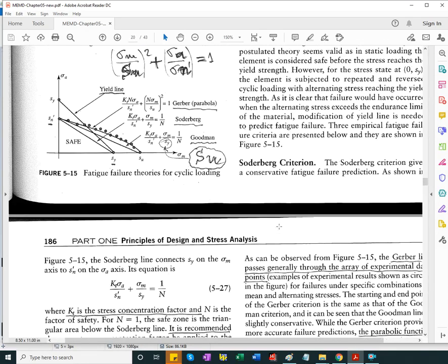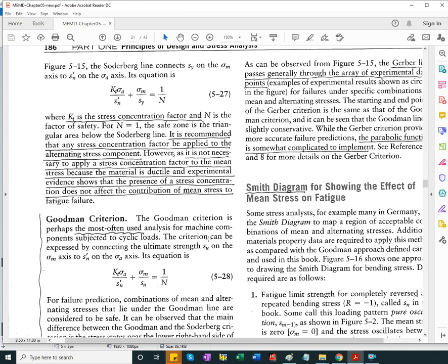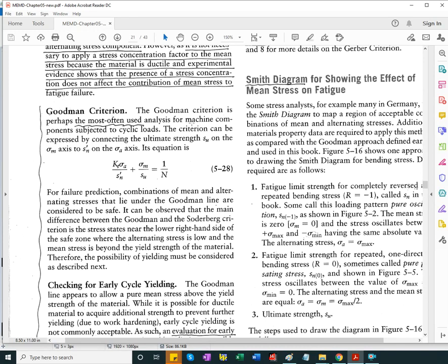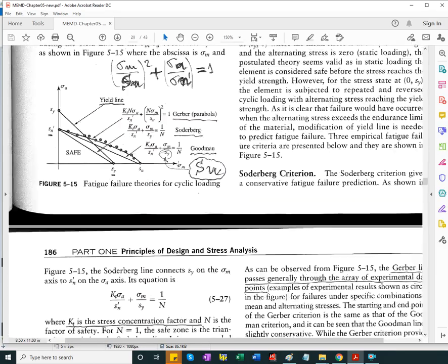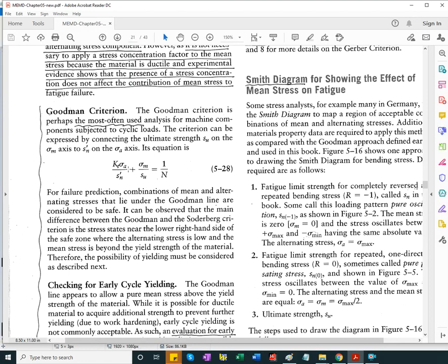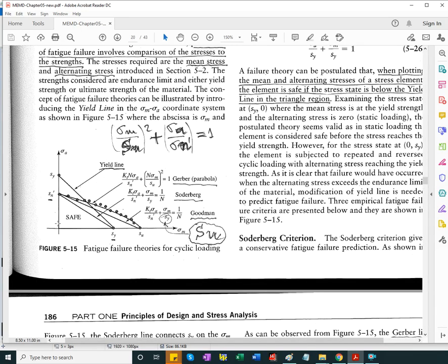And if we're to calculate the design factor, again with the Goodman line being our preferred theory for mean alternating stress calculations, this is the equation to use, which you can see is correct, SU here versus what's on the figure. Find mean stress, find alternating stress, calculate the stress concentration factor, if any, and then you can calculate the design factor N. Design factor is the same as we did for the modified Mohr theory for brittle material.